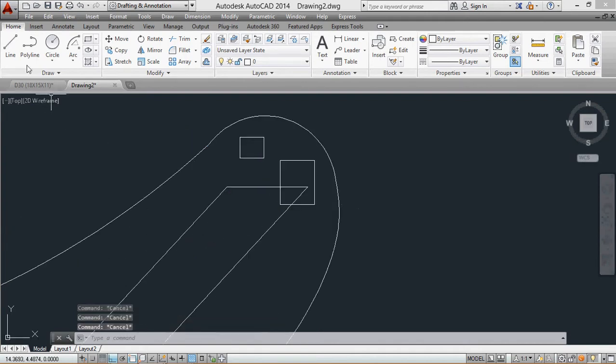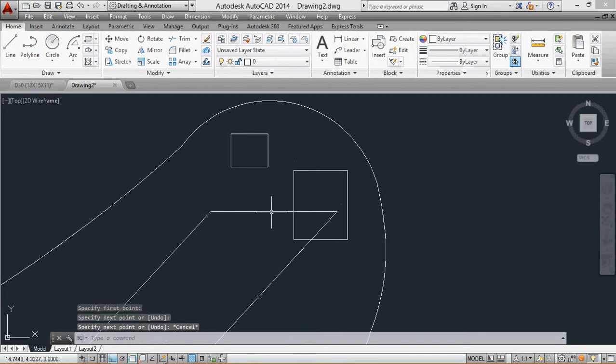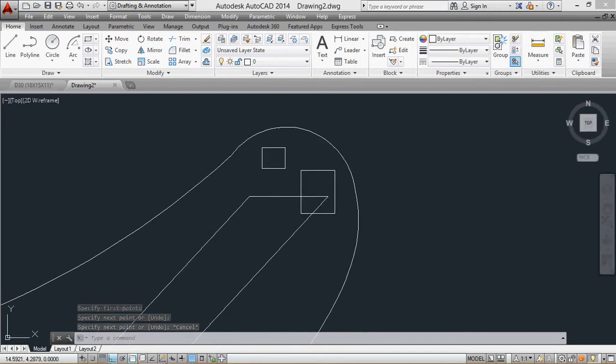So sometimes you just want to select a line that's stuck, hidden behind another line. What you can do is create a blue box just big enough to catch that small line, but not big enough to catch the whole item, and you get that line to delete. So it's a pretty neat trick.